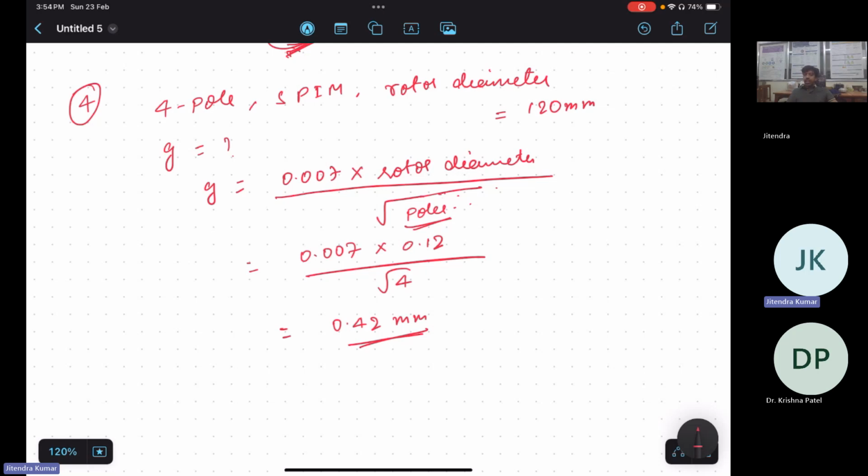So what is the doubt exactly there? First, the outer stator core diameter. So see, Di by Do is given, isn't it? And D square L you can calculate for this machine. So in total three things: outer stator core diameter, core length and the inner stator core diameter.